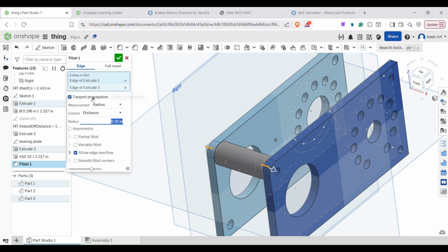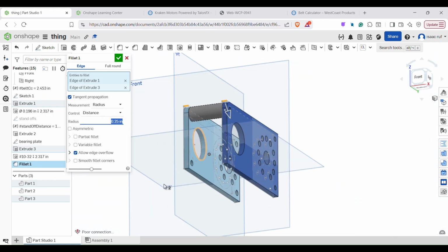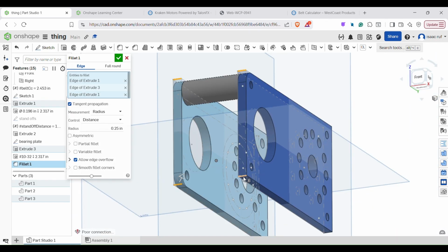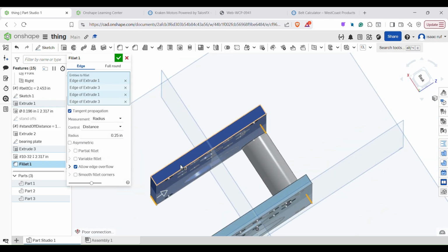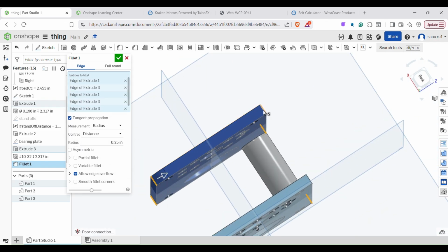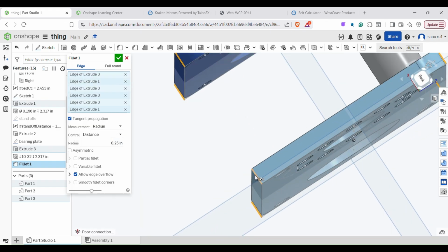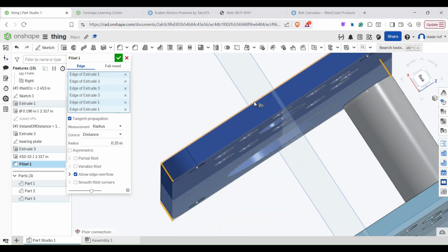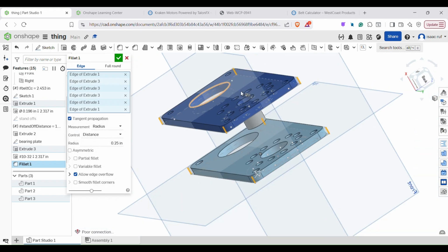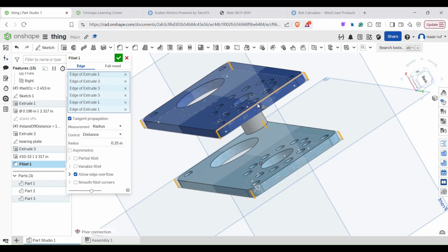And you'll see it will line up right with our standoffs. So we do this, click all of these vertical faces that you want to fillet. Now I'm going to do something to break it just to show you something. You can't fillet something more than the material you have. So remember, this is 3/16 material. I can't do a 1/4 inch radius on it. You're going to see it's going to break it and it's going to make everything red.